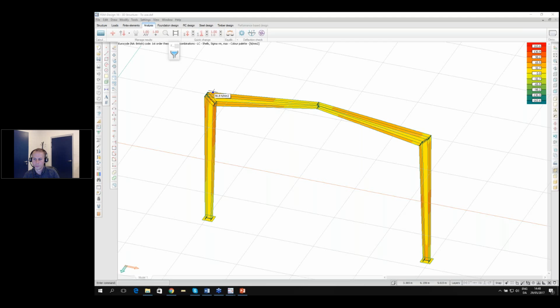The bolt connections, just keep in mind that if you do bolt connections, you just have two shells with a distance between each other, and you do a point-to-point connection. The reason you do that is you get the forces out, like kilonewton tension or compression, and you get your shear. So you get your forces out where you can design the bolt for this force, and all forces go through these connections. The same with weldings, it's just line-line connections. So it is basically just connections.